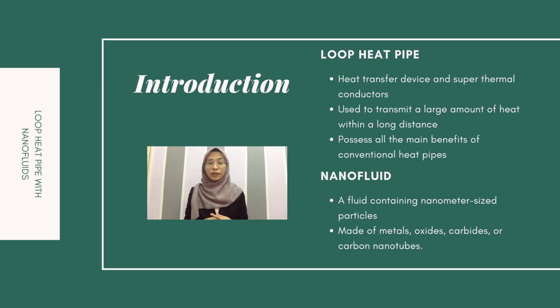So let's start with the introduction of loop heat pipe and the nanofluids. So loop heat pipe, it is used to transmit a huge amount of heat within a long distance. It is also known as a super thermal conductor or heat transfer device. The loop heat pipe has many advantages and it possesses all the main benefits of the conventional heat pipe. The advantages of loop heat pipe are high heat transfer performance, long distance heat transfer, and small heat transfer temperature difference.